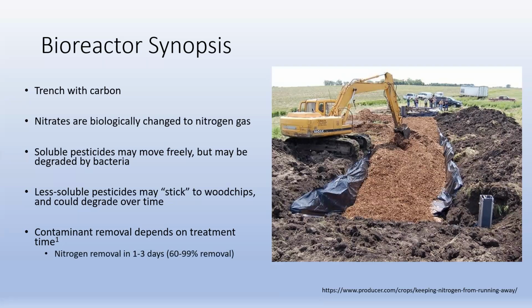So you can get pretty substantial nitrate removal in 1 to 3 days. In publication and Water Research, we got about 99% nitrogen removal, from 90 parts per million to less than 0.2 parts per million nitrate in 72 hours, in that 3-day span. The less time you have, you'll still get treatment, but it won't be as complete.